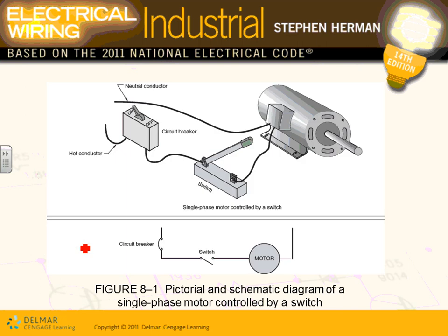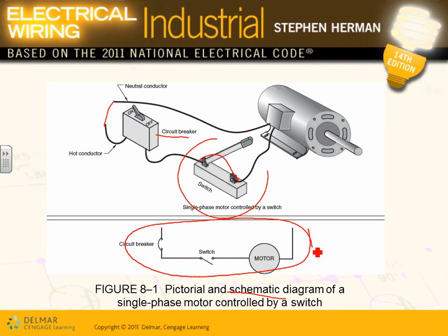Okay, gentlemen, here's the single-phase control. Here's a single line diagram. You have a switch, you turn this switch on, there's your circuit breaker, this is your overcurrent protection device. There's your controller here. You turn this motor on and off with a switch like this. Here are the schematics for it. That's called manual. Can you guys see the word manual? You have to go physically, mechanically push the button to start it and stop it.